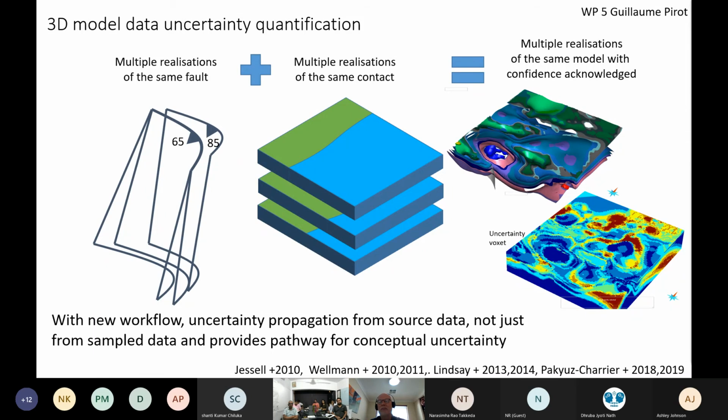So for us, there's just no question, it's got to be an implicit scheme. It brings its own problems, don't get me wrong, implicit schemes aren't perfect either, but if you want to do the uncertainty analysis, which implies making stochastic simulations of variations in the 3D, the only way to do it is automatically and using implicit schemes.